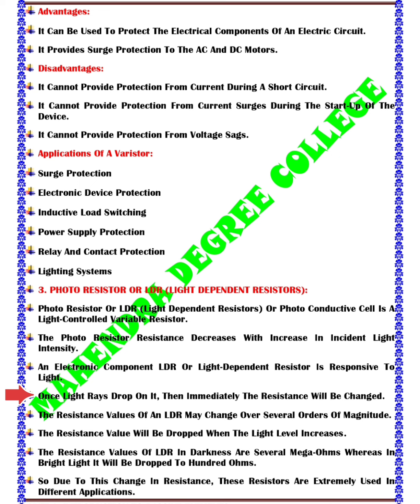This property is due to the phenomenon of photoconductivity, where the material of the LDR becomes more conductive when exposed to light. As more light strikes the LDR, more electrons are excited, and the material becomes more conductive. Since conductivity is the inverse of resistance, the resistance of the LDR decreases as light intensity increases.